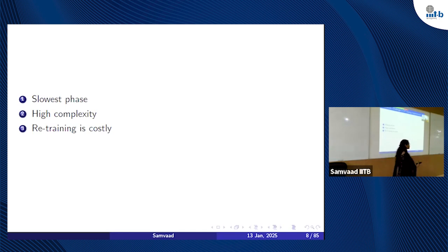And if you don't implement the training on device, then what happens? If you have trained for some application, then you have to again go back and train for some other application in software, and then implement it on hardware. But if you implement the training on board itself, then you can just change the training data, load it, and train the device. The circuit is already there on board, and you can use it for classification. That was the reason behind implementing the training.